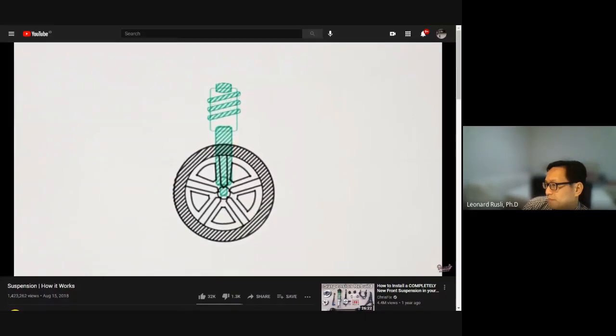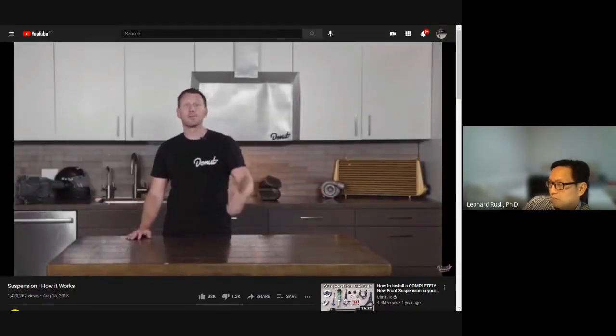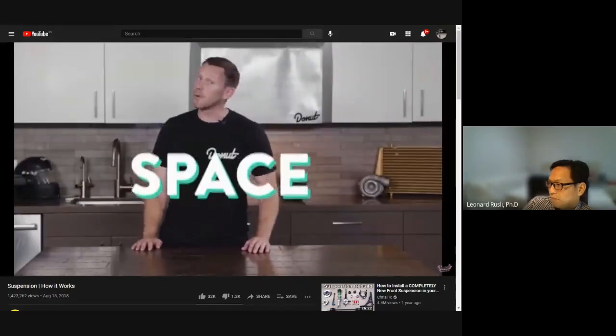as smooth driving comfort. These are pretty small, not too complicated, and not too expensive, so they're pretty common. They don't take up much space horizontally, so they're super common in front suspensions on front-wheel drive vehicles. They do take up a lot of space vertically, though.